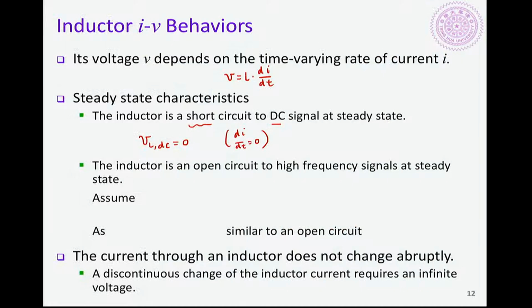At high frequency, an inductor can be viewed as an open circuit. Assuming, for example, the current is a sine wave, the voltage is also a sine wave, proportional to the frequency omega. So as omega approaches infinity, the voltage approaches infinity, which can be viewed as an open circuit.